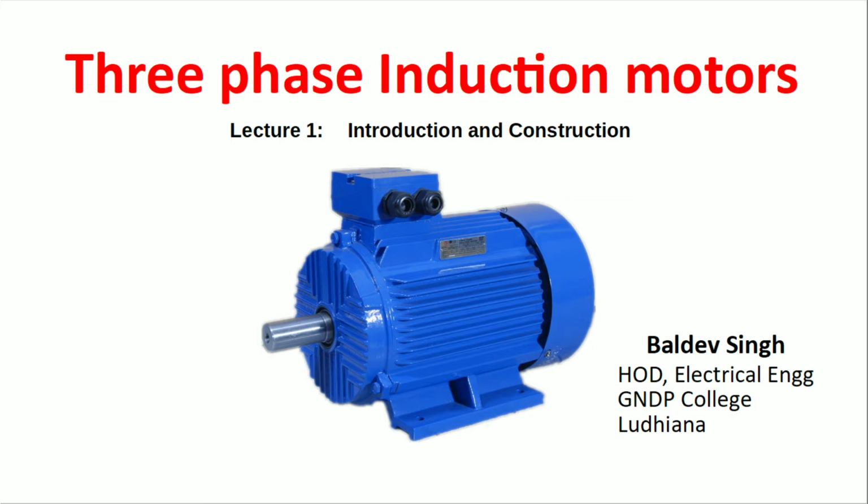Hello, we are starting with the first chapter of electrical machines, that is, three-phase induction motor is our first chapter, and today we will discuss the construction of the three-phase induction motor and have some introduction to it. Three-phase induction motors are very simple in construction because the supply is connected to the stator windings only, which is stationary, and the rotor is not connected to any supply, so construction becomes very simple and rugged.